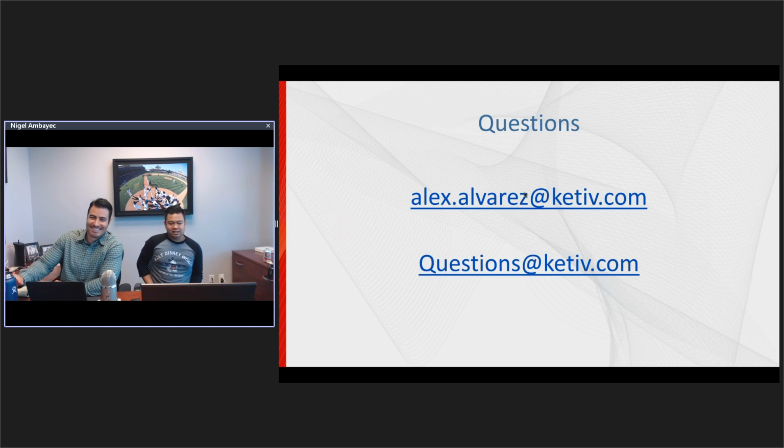So let's go ahead and answer some questions. The first one is, if I'm working with Inventor parts, can you save them as a SolidWorks file format once we have all the parts set up? So it's probably more of an Inventor question there, Will, but I can answer that for you certainly. If you're working with Inventor parts in Inventor, you cannot save them out as a SolidWorks file type. You save them out as a more general file type, something like a STEP file or a Parasolid file that you might be able to bring into SolidWorks later.